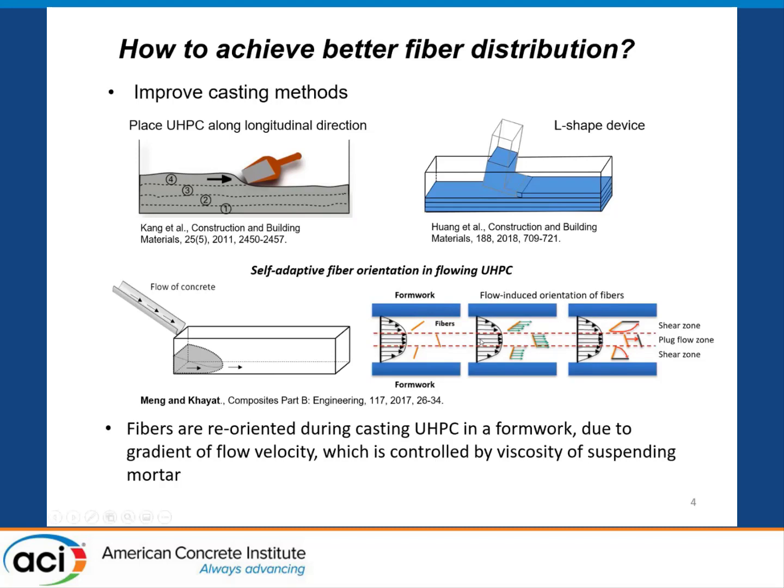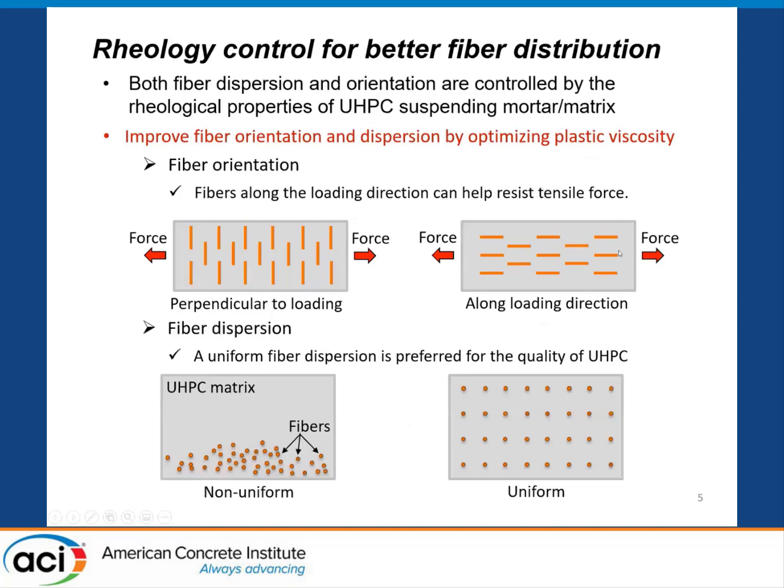Not only the fiber orientation, but also the fiber dispersion is controlled by the viscosity of the suspending mortar. So besides using better casting methods, we also need to optimize the viscosity of the UHPC suspending mortar for better fiber orientation and dispersion.